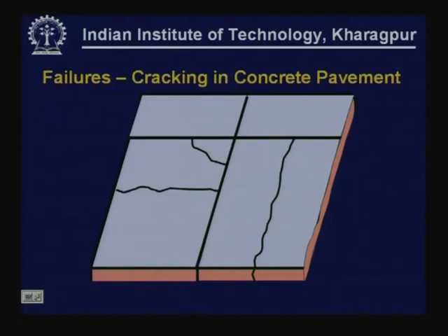Concrete pavements fail in different modes. This being a bound material, cement concrete, obviously cracking is the main mode of failure. Cracks can occur in different regions, directions and locations of the slab. This can occur because of various reasons: load related, temperature related, or cracking brought about by change in volume of either the slab or the other layers in the pavement system, base or subgrade or foundation.